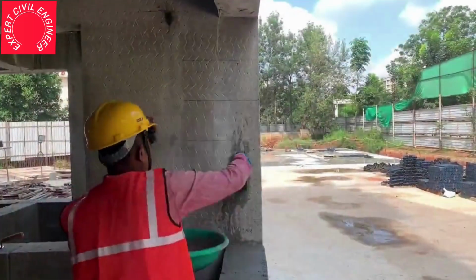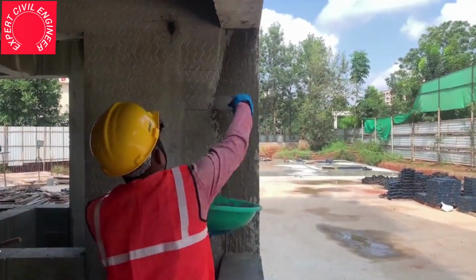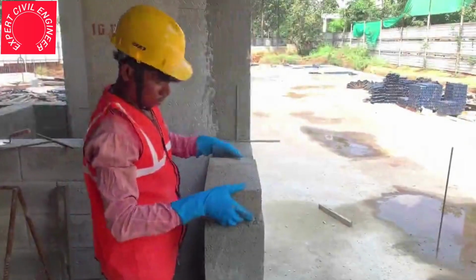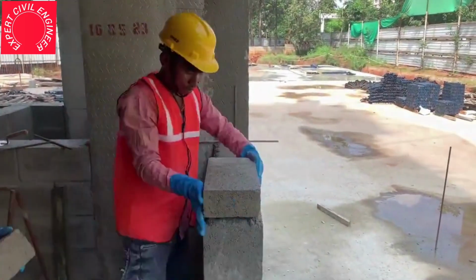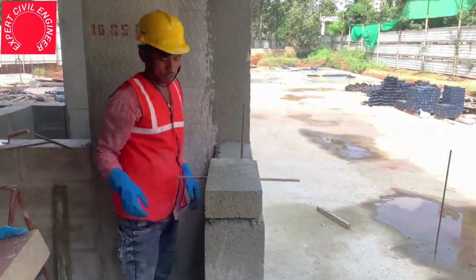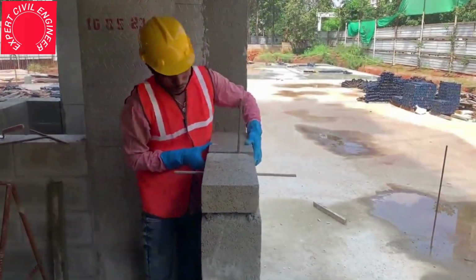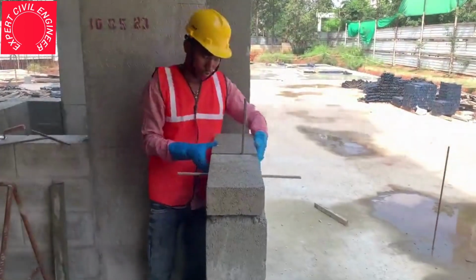A thick cement slurry coat of ratio 1:1 should be applied on the columns to enhance the bonding between the blockwork and the concrete surface. After marking the blocks in the adjacent column, it is essential to check the balance gap and ascertain the adjustable courses' thickness. Cut the blocks to the required size for the adjustable courses and place them above the 1 meter height as needed.